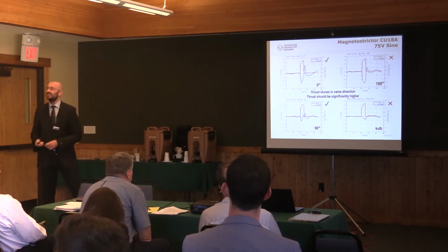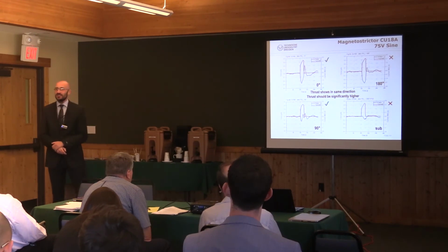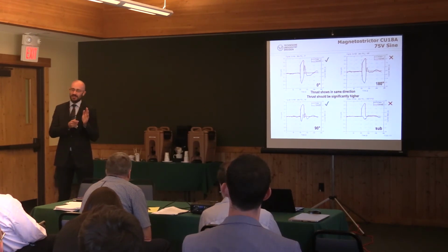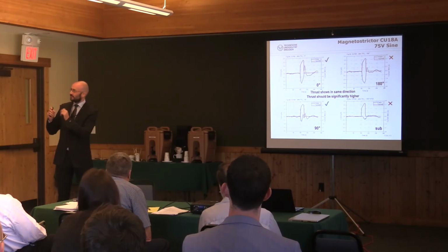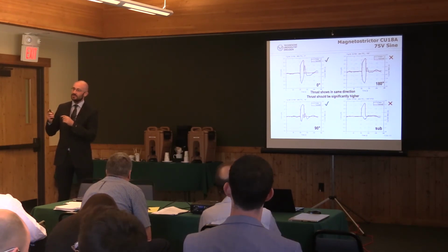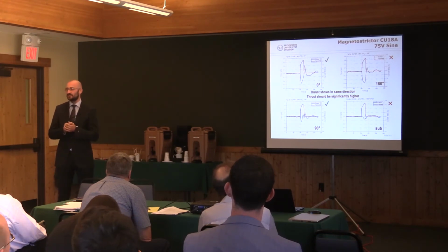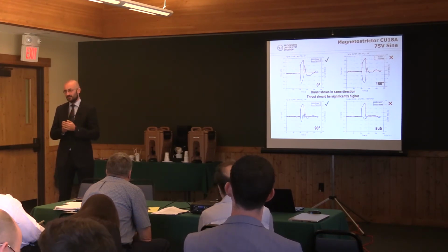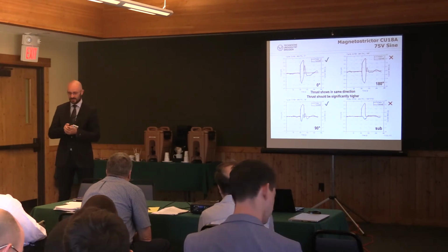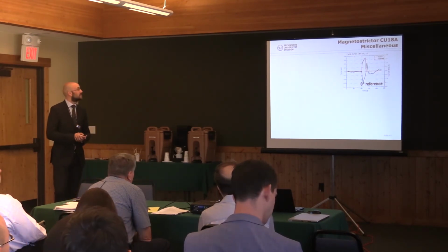Sorry, could you repeat this last point? The magnetostrictor, because it is not a piezoelectric material, has no electrostriction, and if you only apply a sine wave, you don't have the benefit of exciting the second harmonic where the electrostriction is. Basically what Professor Woodward does. So we have to drive it with a mixed signal. Yeah. So this can only be used with a mixed signal.